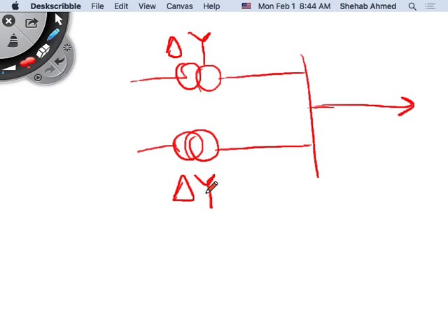You cannot do that, because each of these phases here is related to the voltage that is across it because of the core that it was wound on. That's why whenever we draw the ones in parallel, we would realize that if the secondary is in parallel with this winding here, then they will have the same phase voltage. So we will look at the phase voltage that is generated across each of the phases, and understand, if I want to create a certain phase shift on the secondary with respect to the primary, I have to figure out how to connect the windings exactly. You cannot just take any wire and put it anywhere, right?